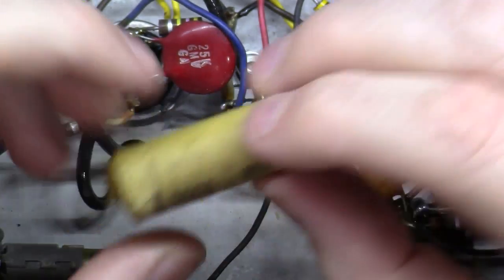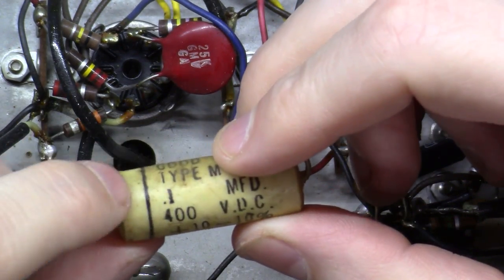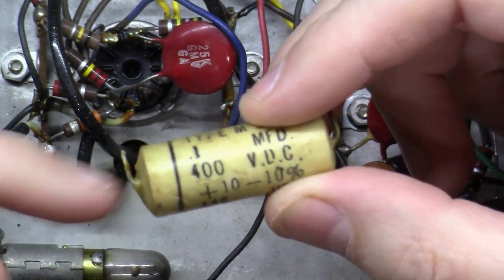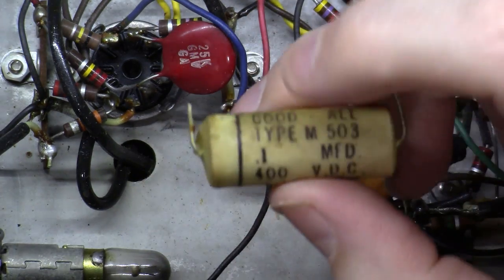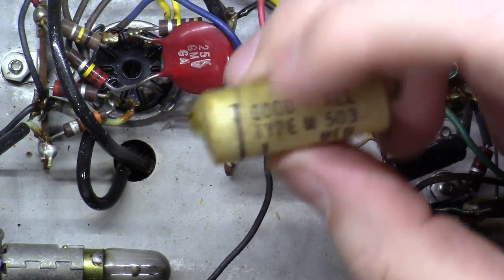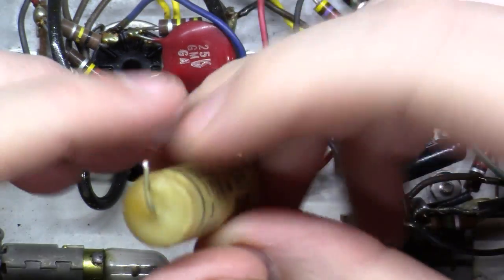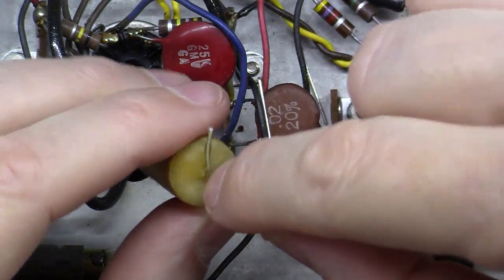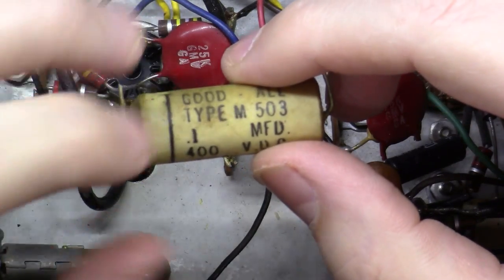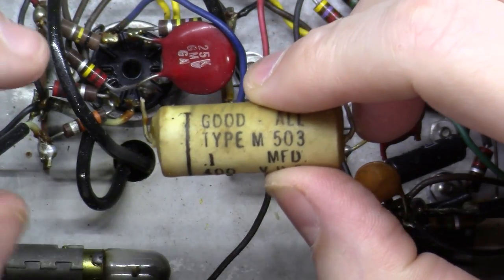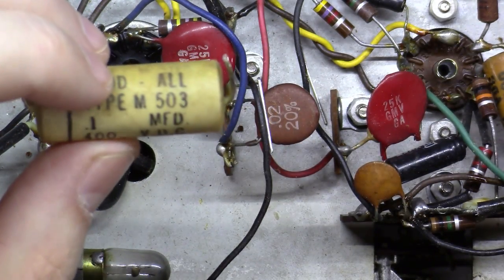You'll notice that this capacitor does have a stripe on one end that in the older days they used to indicate the outer foil of the wrap of the capacitor, and then ultimately if you're replacing it with new ones that were marked, you could do the same. But it's not really as much a positive negative indicator as it is which is the outer foil versus the inner foil on the winding. And there is some belief system that says keeping the outer foil winding in the same direction as it came out can help reduce noise in the circuit.